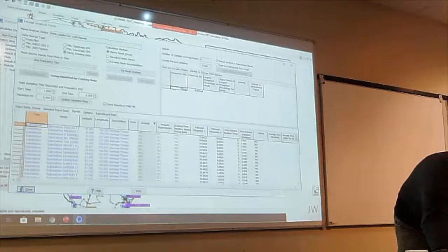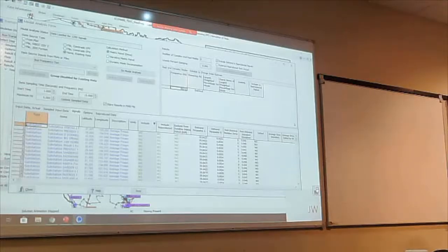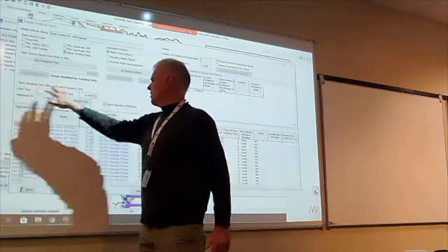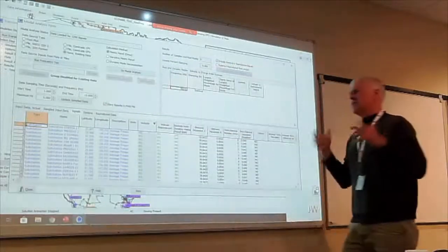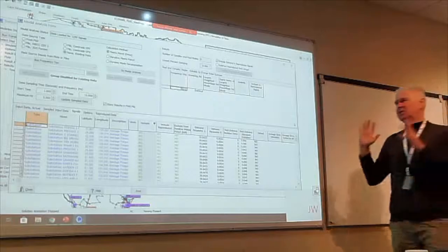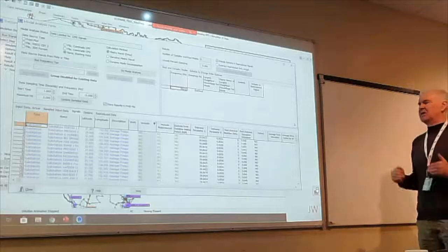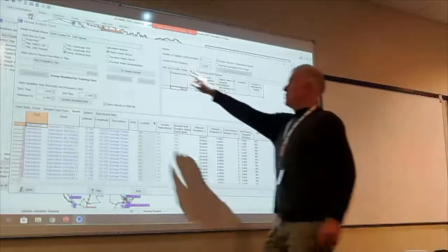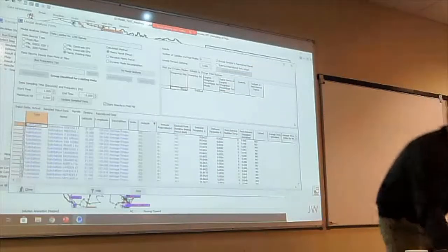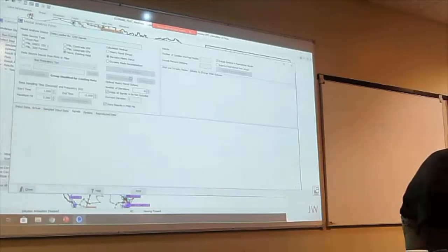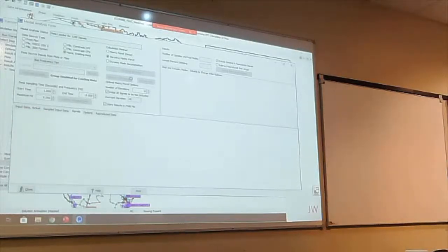If you scroll down here, you have 1,250 signals. We're going to do modal analysis on all of them right now. Again, you have to say what start time and end time you want. It will default in a simple study like this to the time of the last event. So its start time is 1, end time is 15, maximum hertz is 5, so sampling at 10 times a second. We want to do the iterative matrix pencil, which we talked about last time, so just click that. Then it's do modal analysis, and it's done.